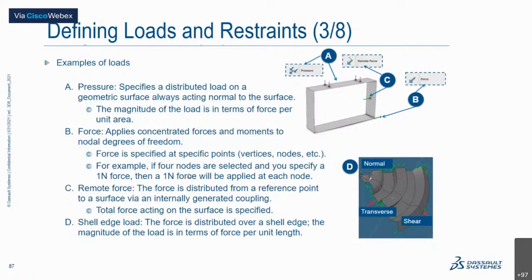Now coming on to, I'll just take you through a few forces and how to apply them. So for example, if it's pressure, pressure is basically Newton per meter square. In this case, once you apply a pressure on a given surface, the area of the surface is selected. So that's how you'll be defining a pressure.